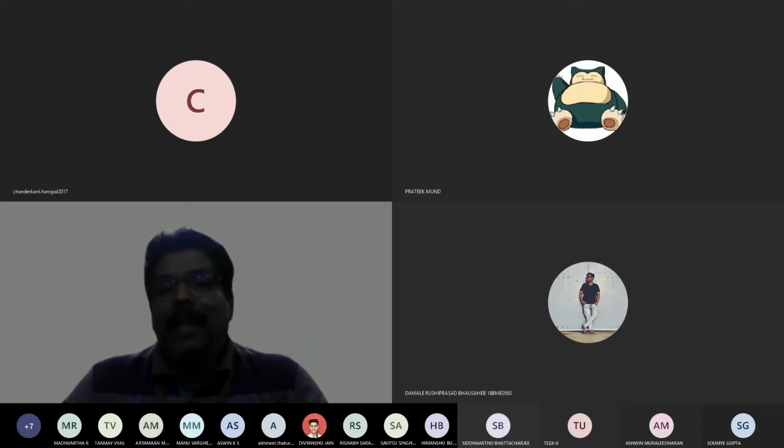And these are the three aspects that we consider in order to define two important parameters which were appearing in your expression of Fy and Mz, which were your stiffness of the sidewall and relaxation length. So we concluded our lecture, how can you find these two using the expression of pneumatic trail. So pneumatic trail has become independent of Ky, and then you are able to have, so we have looked at how can you find out this Ky and Lr is what we stopped at in the last class.